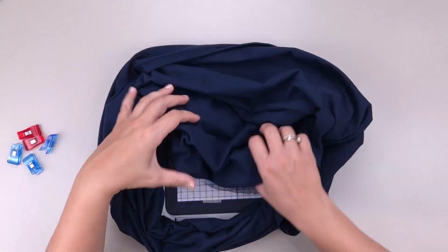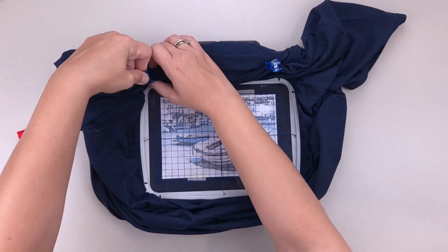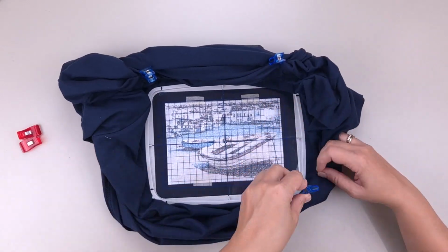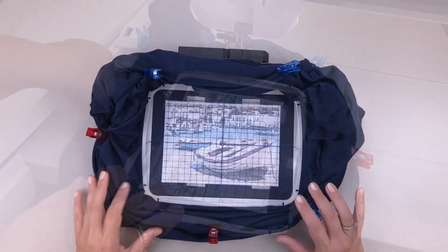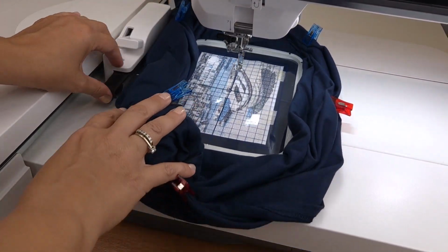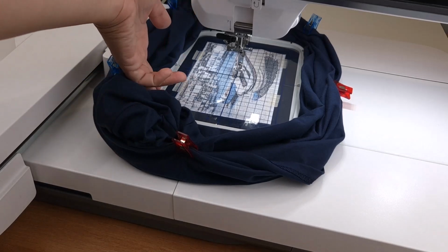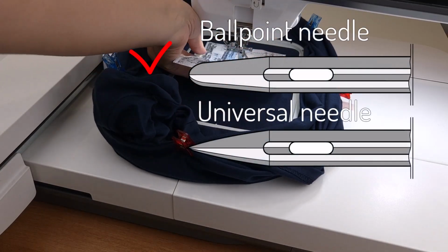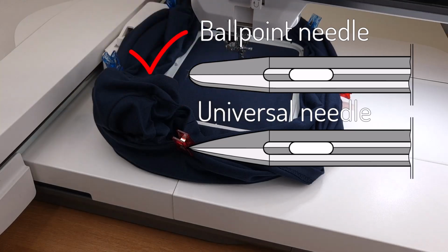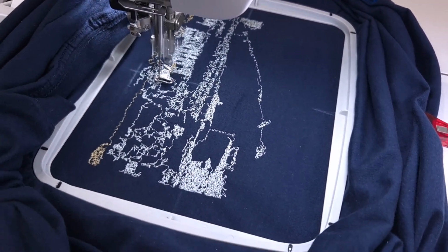Now, roll the back of the t-shirt. Use a couple of clips to hold the rest of the t-shirt out of the machine's way. Place the hoop on the machine and make sure no fabric is cut where the machine will move. It is recommended to use a ballpoint needle for stretch fabrics. Start embroidering following your machine's instructions.